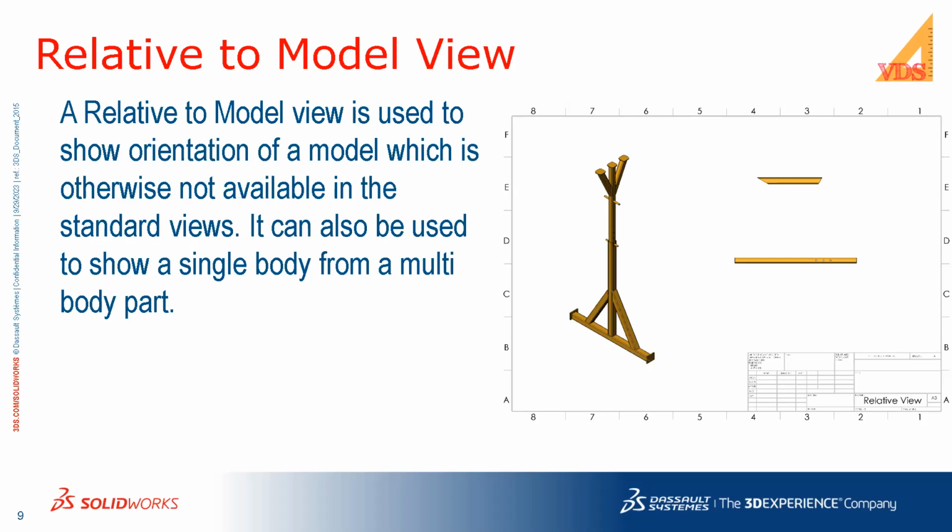Second, we can also use this view to show a selected body or selected bodies from a multi-body part, which otherwise will be a little difficult, because when you insert a part with multiple bodies, all of the bodies will be available in the view, and you have to go and hide each body.